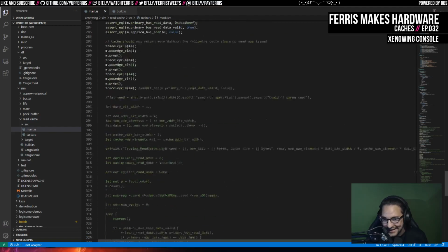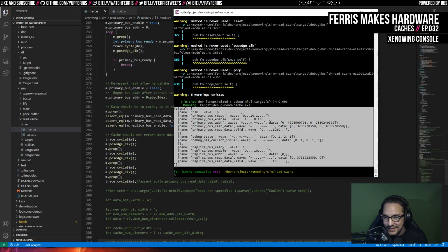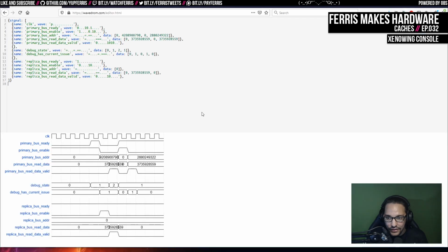That's the whole point. I'm explicitly doing all this state tracking and everything, and then producing this diagram, which is bad. I need to leverage the fact that I have a compiler here and output this directly. Most other HDLs will actually do that. I could alternatively dump Verilog and then run that through a sim, but since I have my own sim anyway, I want this to support that. I haven't implemented it yet.